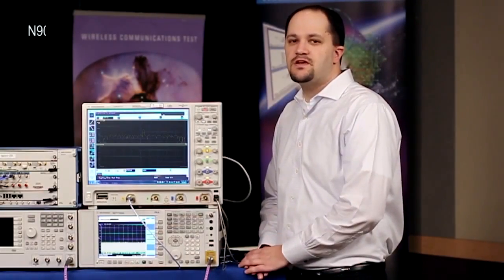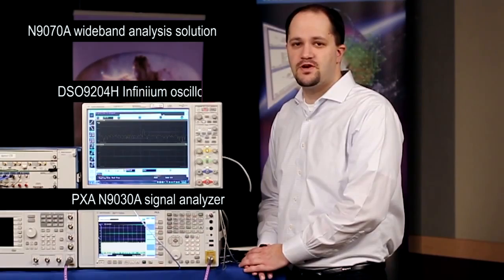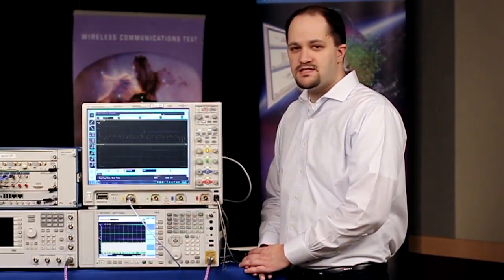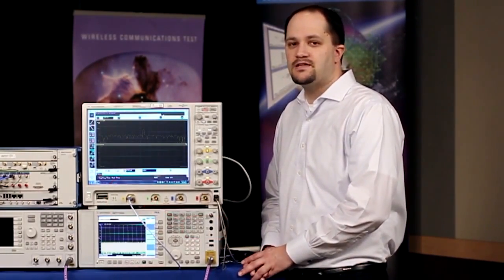So the setup consists of 3 things for the N9070A. The first is a PXA signal analyzer, the second is a high dynamic range oscilloscope, and finally the vector signal analysis software. The PXA's IF output is connected to the channel 1 of the oscilloscope. In addition, there is a LAN cable connected between the oscilloscope and the PXA signal analyzer.